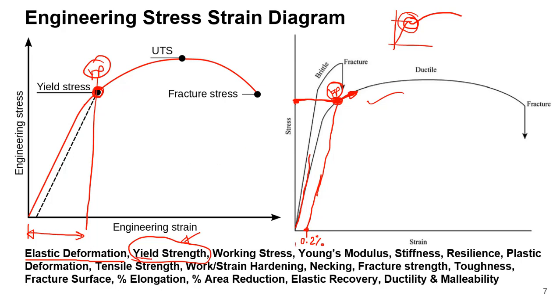Now remember, the strength of the material is something which is constant for the material, and the stress is defined at each and every point, because it depends on what load is applied. But the strength does not depend on what load is applied. Strength depends only on the material. It's a material property, corresponding either to the yield point or to the maximum stress in the engineering stress strain diagram. So strength is a constant for that material.